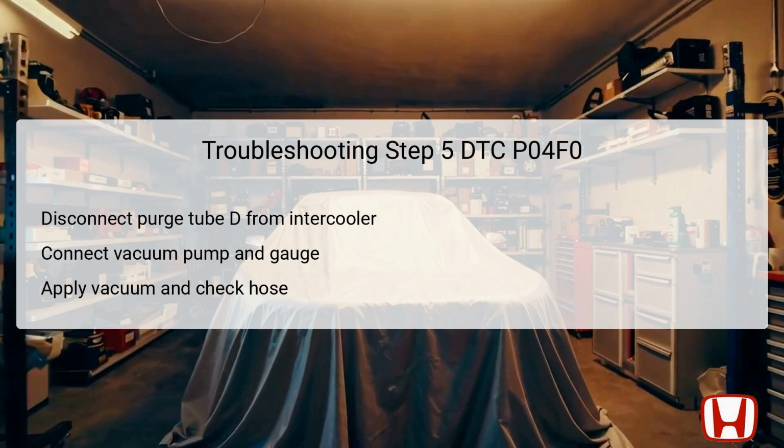If it fails to hold vacuum, it indicates a blockage, requiring further inspection of the run from the intercooler to the EVAP canister purge nozzle.